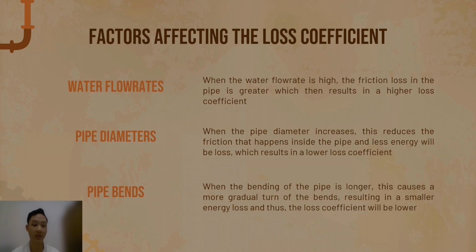And for the last part, which is pipe bends, when the bending of the pipe is longer, this causes a more gradual turn of the bends, which results in less energy loss and thus the loss coefficient will be reduced.